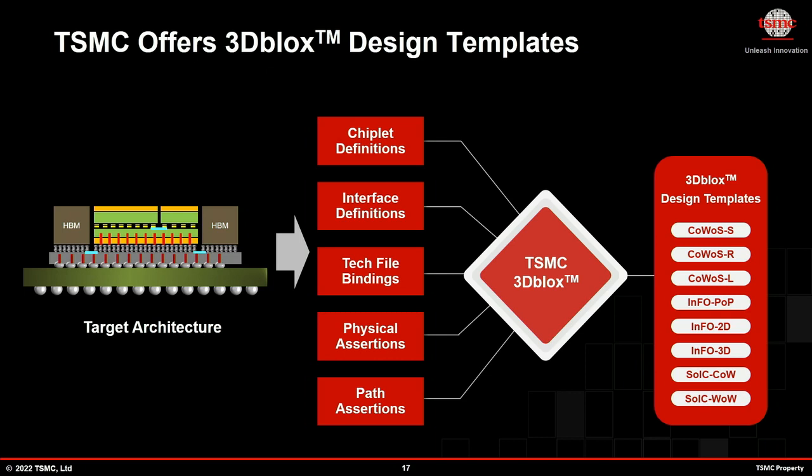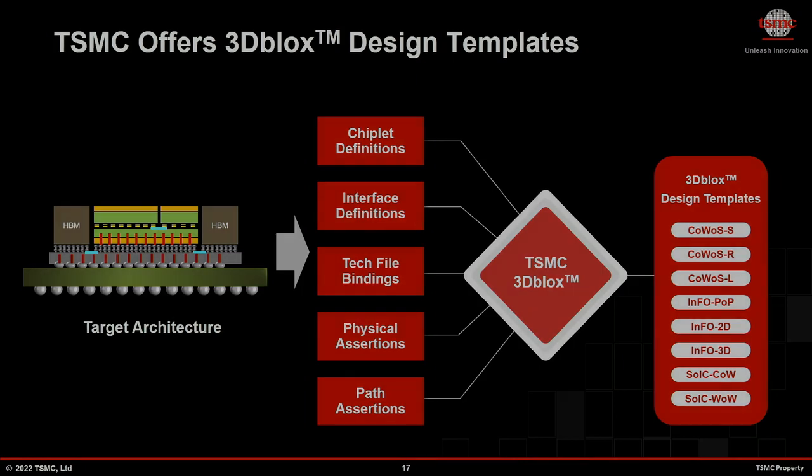But with 3Dblox, since for a particular architecture the chiplet has already been defined clearly, and the interface defined clearly, we pre-bind all the TSMC tech files such that it can be used directly. And we make sure all our offerings have this kind of design template. And what can you do with this template?